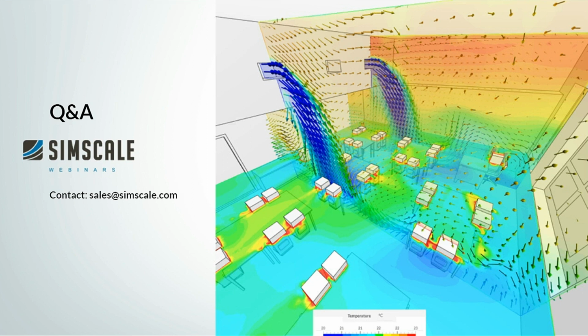There's also a question on how we calculate the thermal comfort parameters. That's interesting because within SimScale, when you're running the simulation, you'll be able to set the metabolic rate, the clothing coefficient, and the relative humidity, so that this accounts for the calculation of thermal comfort parameters.